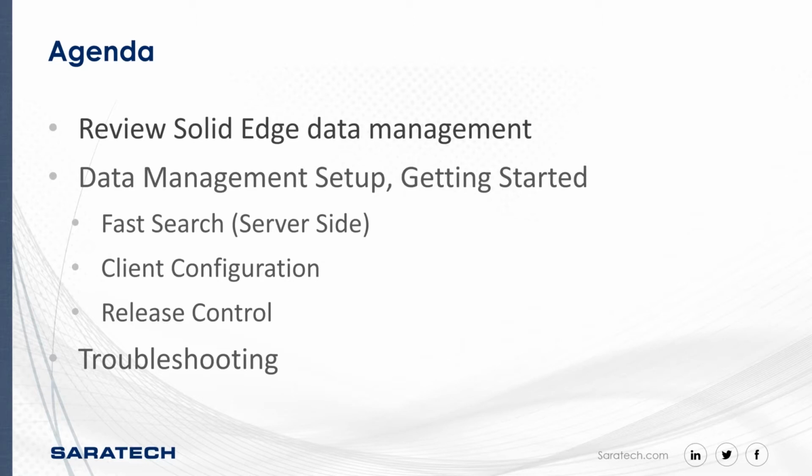So today we're going to do a quick review of what we talked about in our last session. You can find that on the YouTube channel, as Sarah mentioned. Then we'll get into the actual setup of the Solid Edge data management. A couple of aspects of that are the fast search, which we're going to show setting up on the server side. After that, we get into the client configuration and some of the folder settings for release control, and then troubleshooting.